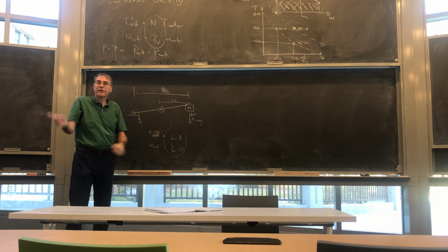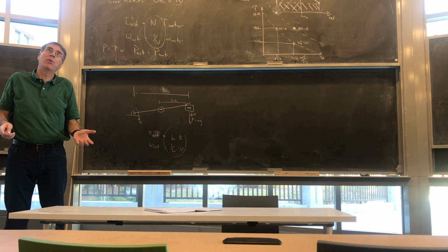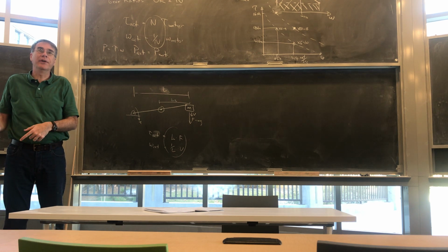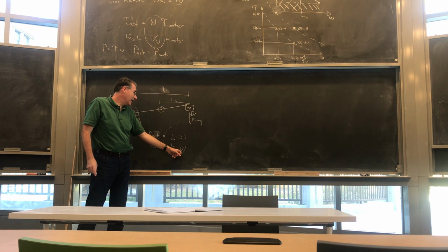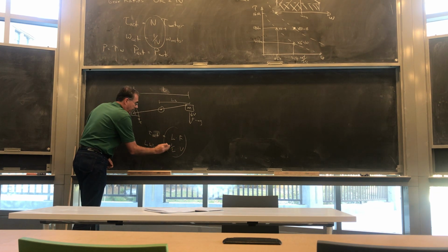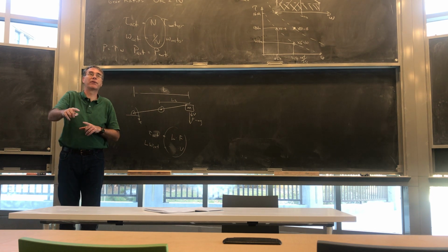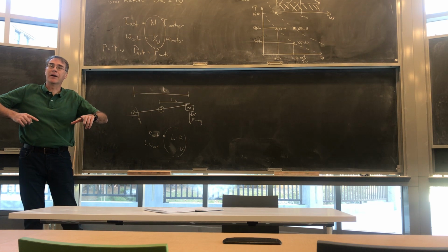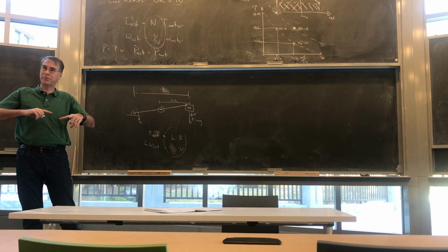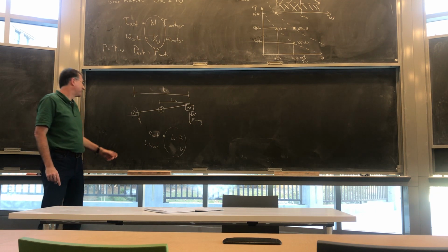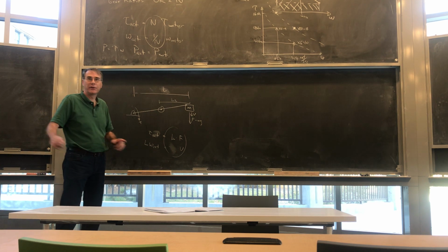A length is effectively a gear ratio, right? It's a lever arm. So for the teams that want to get a really fast movement, if you want a fast V, you want long L's. There's also a question of what your lever arm has to be in different places. Maybe looking at the air hockey players that are talking about trying to get some faster motions in there, we should think a little bit about what those lengths are going to be.